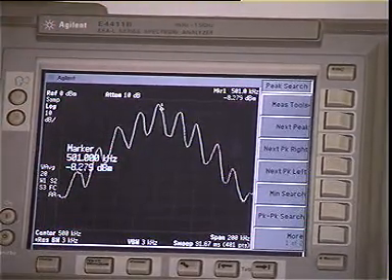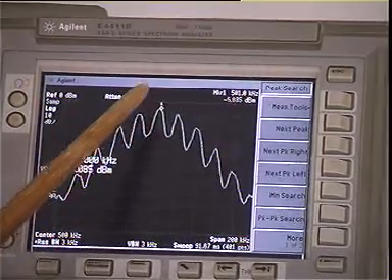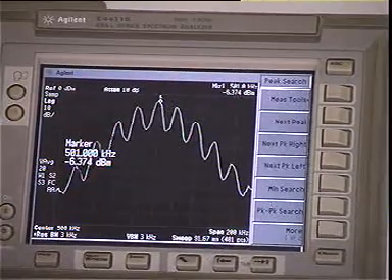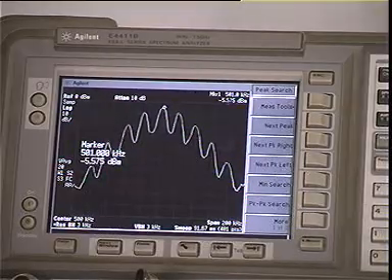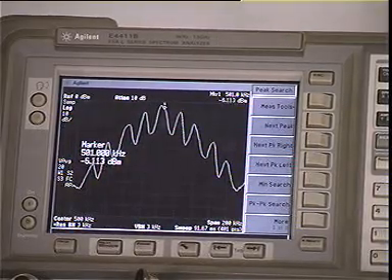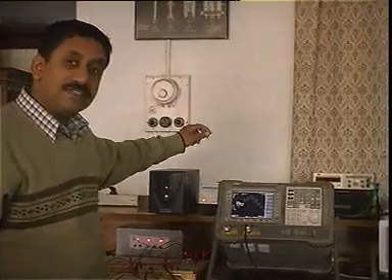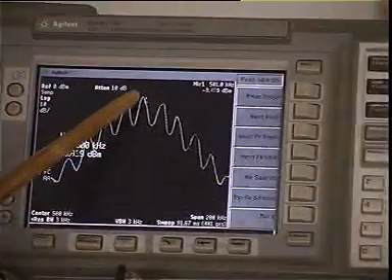Then, if I continue to increase the message signal amplitude, the carrier power will then begin to rise. It will reach a peak, again it will begin to fall, and it will go towards the second null. The second null happens at a value of about 5.4 or so. So by looking at the first null, second null, third null, and so on, I can find out the value of beta. At these values of beta, J0 beta will be equal to 0. We'll just see that. Now we want to increase the amplitude of the message signal. Just note how this peak will slowly fall down.